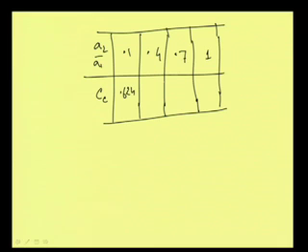A2 is the downstream area, the smaller one, and this is the bigger one, so the bigger one is 10 times larger. So for 0.1 we get 0.624, then 0.659, then 0.755. With the increase of this ratio, this coefficient is increasing. When it is 1, there is no value of Cc, because there is no contraction. So using that relation we can finally find the value.